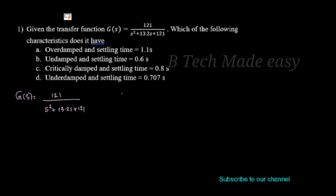From the standard characteristic equation formula of a transfer function, it is s² + 2ζωn s + ωn². Here, zeta is the damping ratio and omega n is the natural frequency of oscillations. By comparing these two equations,